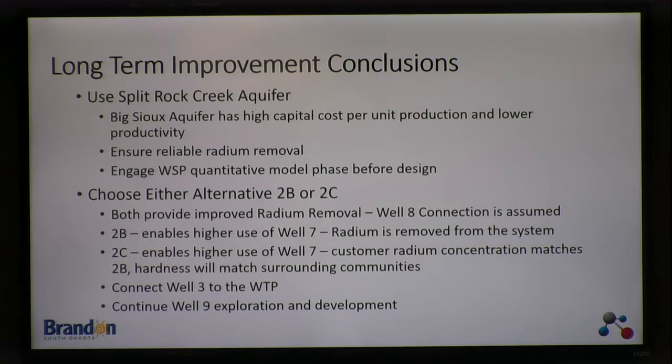With RO, you have another barrier to that water. So essentially you're engaging a second barrier to treatment, to remove radionuclides. With WRT, you have an additional barrier. So other than the A alternatives where you have the existing treatment process, each of the other treatment processes improve water quality by, number 1, having an additional barrier for radionuclide removal, and number 2, for B and C and D options, having reverse osmosis that gets you to a water hardness that's close to what the neighbors are.